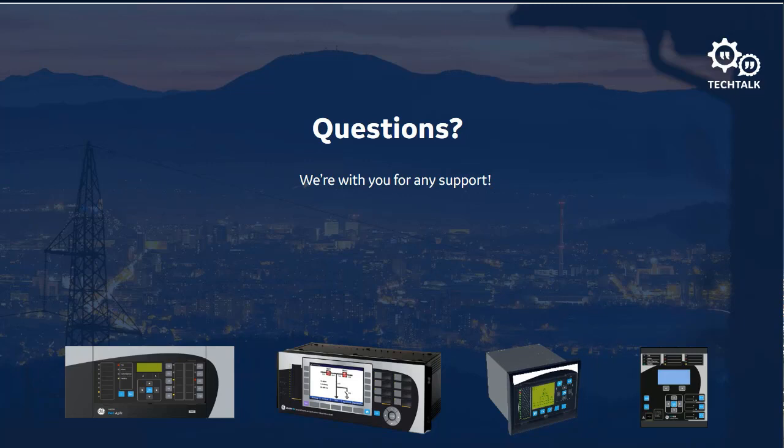You asked me to clarify the application of the 3V0 ground fault detection scheme. And I think what you're asking there is, for an ungrounded system, can you clarify the 3V0 ground fault scheme? Basically what you can do for an ungrounded system is connect a set of VTs in what I would call an open delta, which is a different connection than a broken delta. A broken delta connection is where I take 3 VTs in delta, but where I'm making up my last connection,